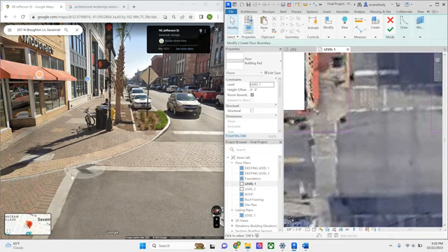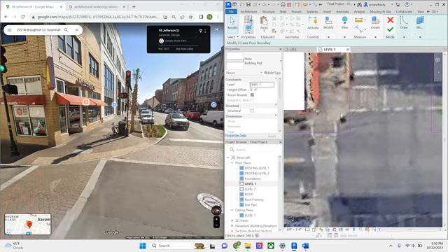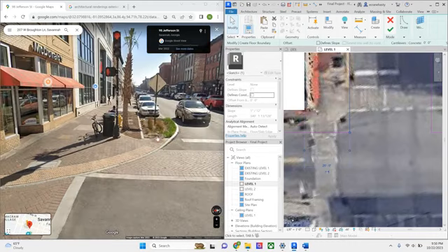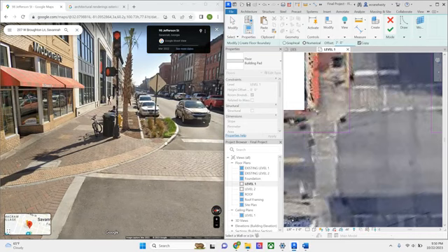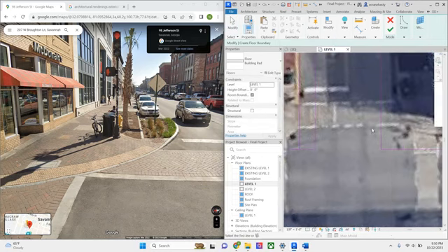representing how this curve is, but notice that this actually comes out probably to the 7 feet. Because it's showing this little inlet for the drainage, and I want to represent that in my model here. So I will offset OF and make sure that my offset reads 7 feet, and trim to get